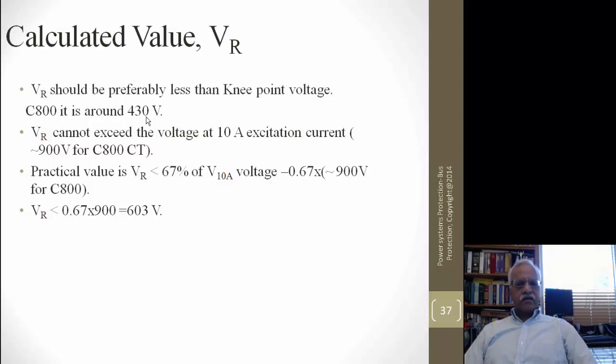And then, as I mentioned, when there is a fault, it develops a voltage high enough across the relay, and your setting is set to twice that amount. For example, in this case we selected a V140 and then we set that to 280 volts.